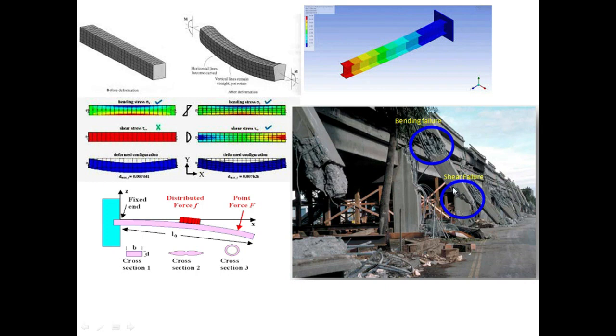Shear failure, you can see it's acting at an angle of approximately 45 degrees. It's not going to be exactly 45, say 40 or 41, 47, 48 degrees, somewhere around 45, if I make this column vertically straight. So if you look at this failure in a beam, you can instantly say that it's a shear failure. Why is shear failure very important to us? Because a shear failure will be generated as a result of the shear stresses exceeding the shear strength limit of that beam.